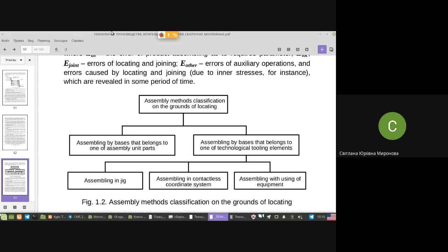As a result, you have a grid of locators which repeat the surface. We may find such pictures, but right now we don't need it. Usually, if we need to locate the whole surface, we use either parallel locators or locators perpendicular to each other, but we do not try to repeat the whole surface in a jig.